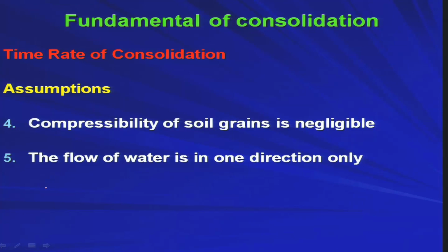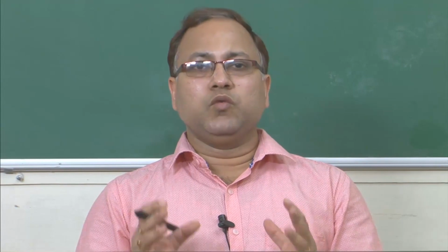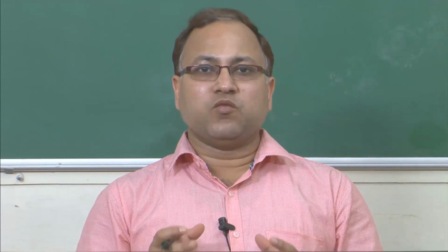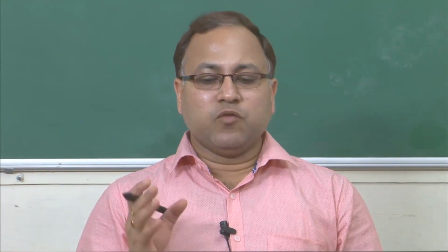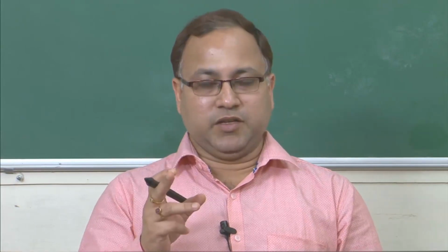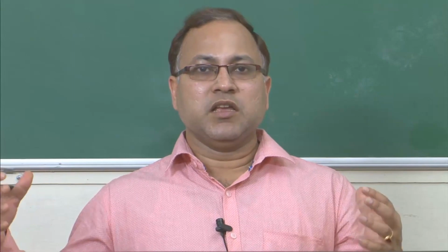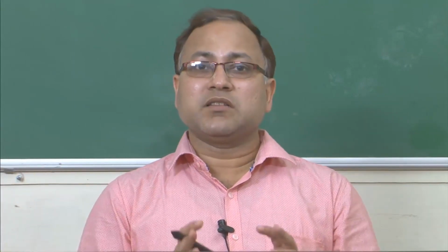Then the fifth one is that the flow of water is in one direction only. When we are trying to establish the 1D consolidation theory, the flow of water is in one direction. You can have flow in different directions, all three directions, but we are not considering that for understanding the 1D consolidation theory.